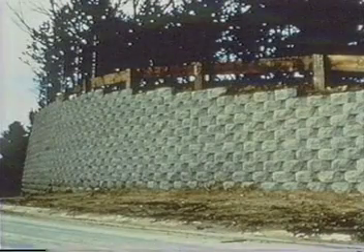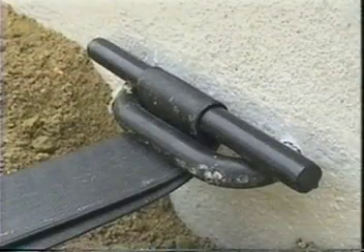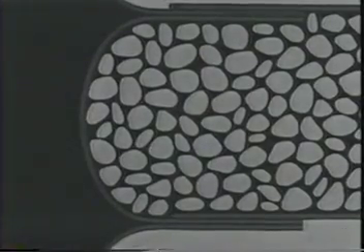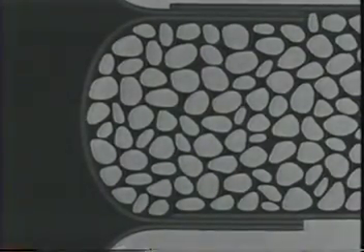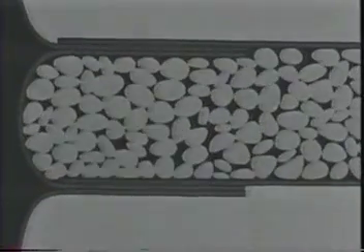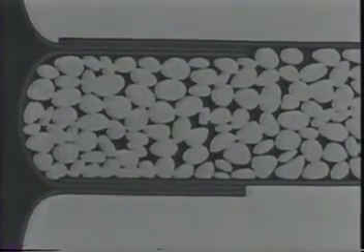Once assembled, segmental blocks or concrete panels must be able to compress vertically en masse. Otherwise, differential settlement between fill and facing might shear the connection between facing and reinforcement. To overcome this potential problem, Vidal's elliptical facing units compressed vertically, like a concertina, in sympathy with the fill and embedded strips.